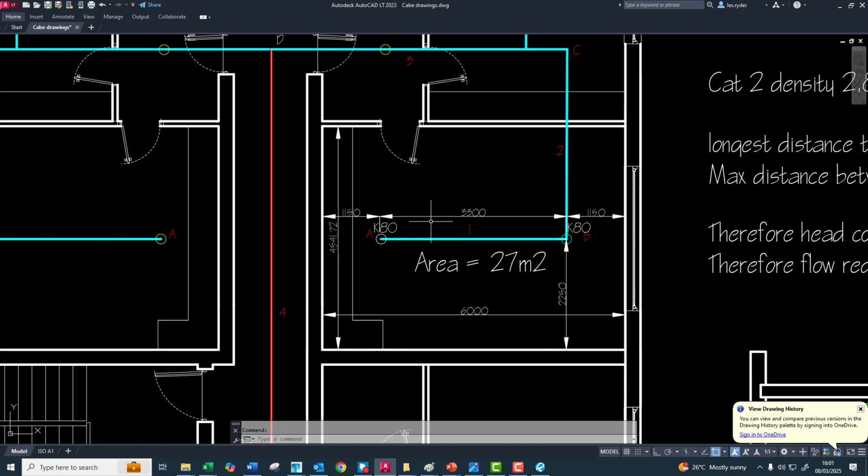and we look at that, and this pipe is 3.3 meters long. So now what I'm going to do is work out the pressure drop on that piece of pipe. And basically that will be the lowest, and the pressure experienced by each sprinkler head further down the line will be greater, because remember, this is the most remote head. Okie dokie, so that's 3.3, and we're going to start off with a 20 mil pipe, and you'll see why